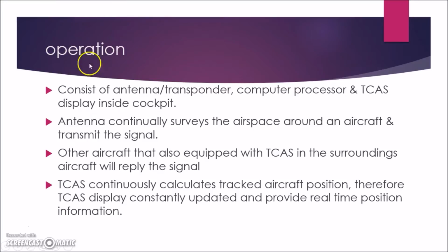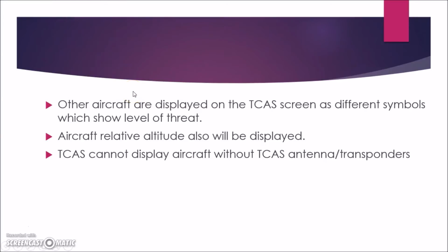If the aircraft could collide in 40 seconds, the system gives out a traffic advisory. This is just a warning that there is nearby traffic and that an action may need to be taken soon. If the distance reduces so that the risk of a collision gets to 25 seconds, a resolution advisory will be given. These are instructions to climb, descend faster or level out. The pilot is required to comply in 6 seconds. The instructions have priority over ATC instructions.